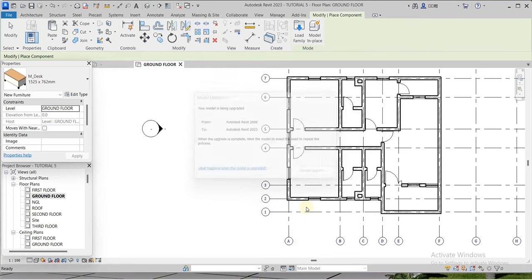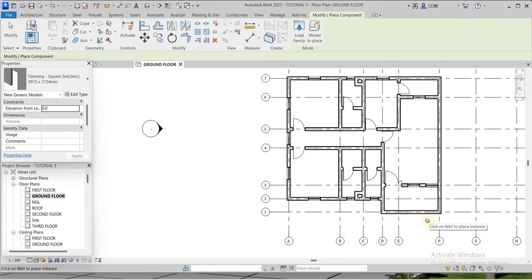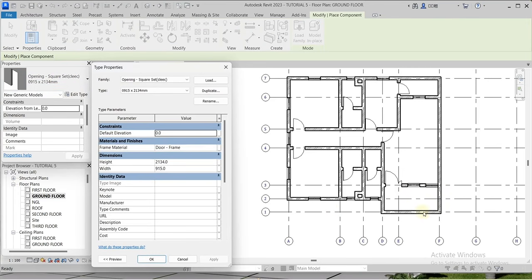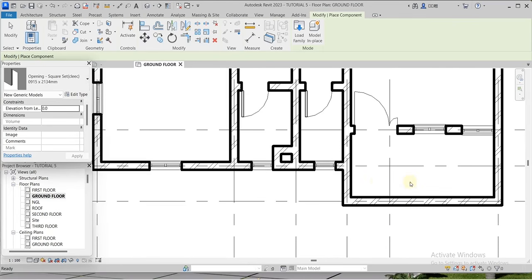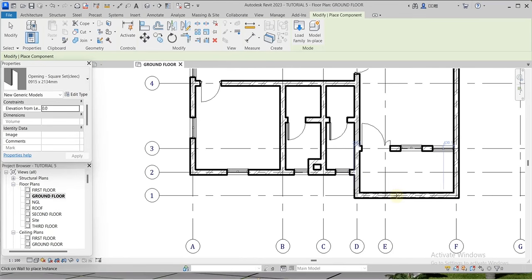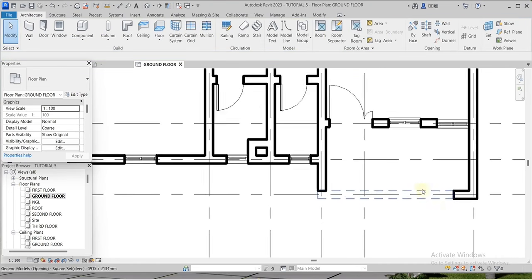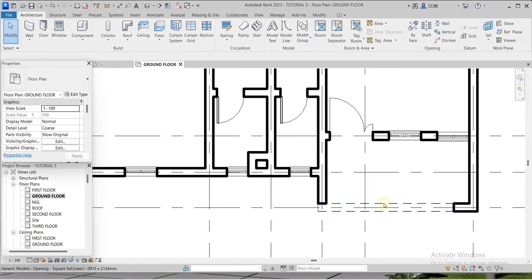Open it. Now what you need to do is to set the height and the width that you want to cover. So I'll use a width of 3,800 and a height of 2.4 meters. That means 2.5 meters. Okay, fine. Take it down here to where you want to open it. As simple as that. We have the opening and we have this dotted line too.